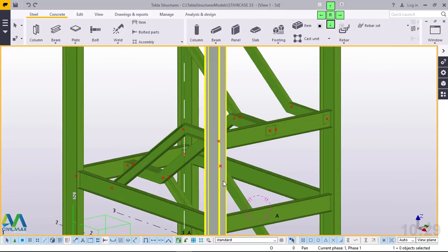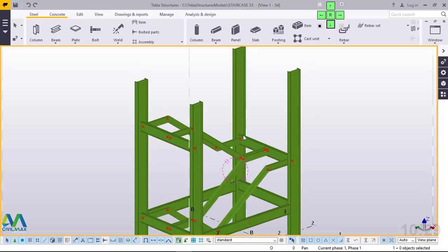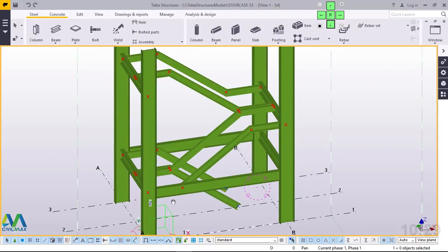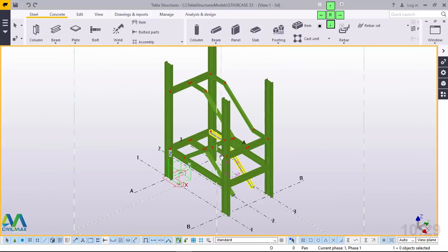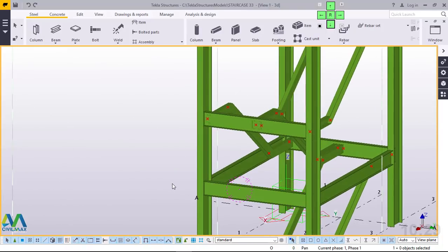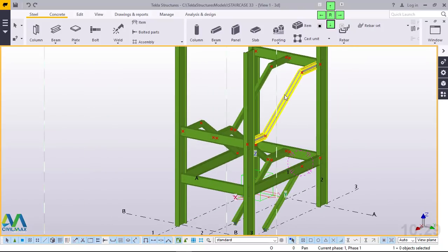Here we are. Now if I press this, I'll be able to rotate this comfortably. Now I want to get rid of these points. I'll right click and come to redraw, and redraw will do away with all these points, because the points are just to guide us in creating the stringers or the flights for our staircase tower. Once we are done with these flights, because these flights will assist us a lot, to make work simple we'll just copy them right away to the height we want.